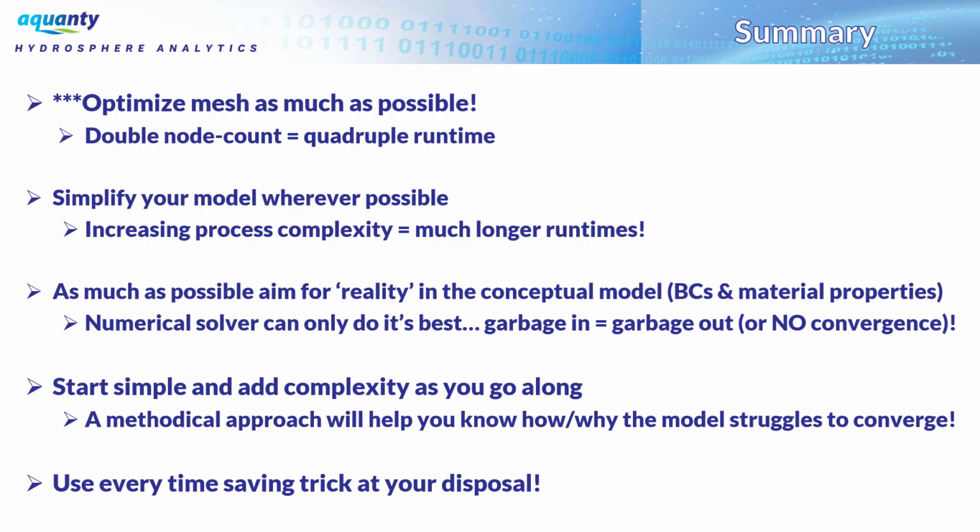As much as you possibly can, aim for reality in your conceptual model. That applies to both boundary conditions, material properties, as well as initial conditions. And use every trick that you have up your sleeve to try and make the most out of every one of your models. All these time-saving tricks, they really add up. Even if they only save you a few minutes, due to the iterative nature of running models over and over, those minutes add up.